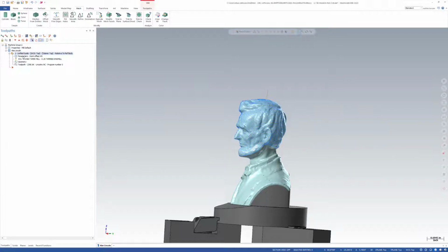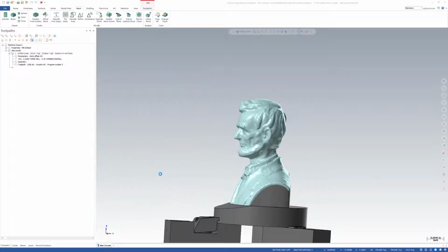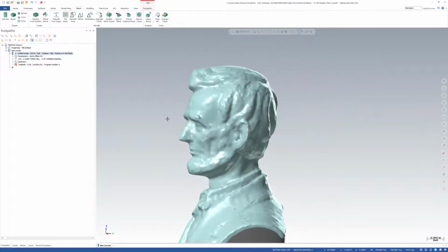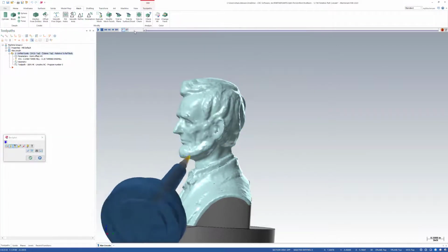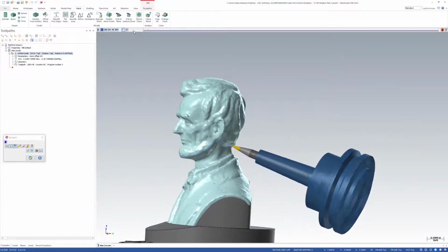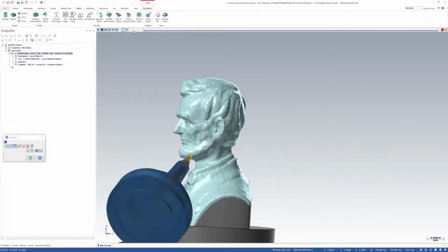And again, in this case, since we're driving to a mesh, as far as tilt motion goes, turning on smoothing actually will visibly change it. Even the backplot will look a lot better, because we're staying normal to each of these facets on the smoothed body anyway, and that creates a really faceted tilt strategy which also creates lots of reversals. So if we just run this with smoothing turned on, you'll see this is far nicer motion. That was extremely easy to create.